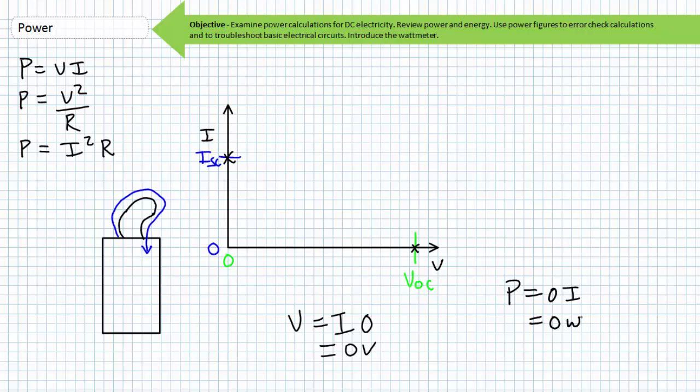What we've been doing is considering the performance characteristics of the PV panel at the two extremes of the IV curve, or the current and voltage curve of a PV panel, where the product of the two intersecting numbers is the power output by the panel. Instead of a short circuit or an open circuit between the two terminals of our PV panel, we can place an electrical load where the voltage across it and the current through it, i.e. the product, is the power supplied by the PV panel.